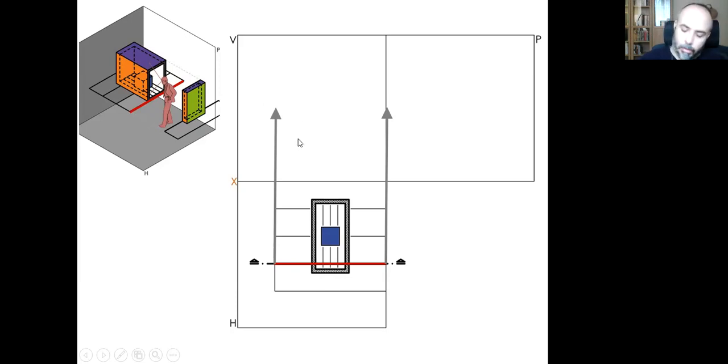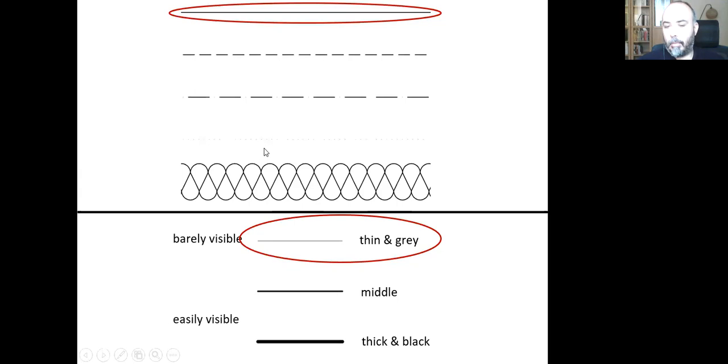And again, I need to repeat that you can just copy from your previous drawing. It'll be easier for you. And in order to transfer the distance, the width, I need to use, again, continuous lines with the thinnest and the grayest line that I can create.